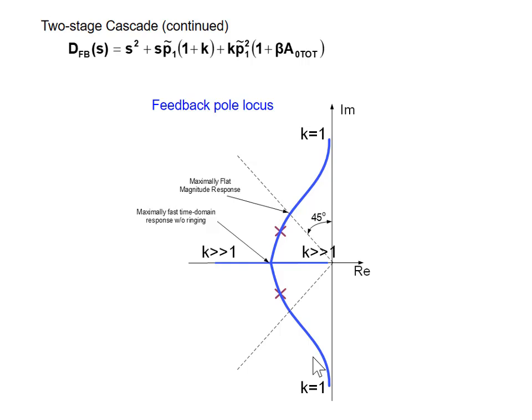Yeah. The comment was we usually try to separate the poles so that they lie between here and here, just slightly, maybe barely on the negative real axis or slightly off the real axis, but not any more than 45 degrees up. Why don't we go ahead and, it's easy to make K bigger and push them down here so they're widely separated on the negative real axis as well. Very easy to do that. Any idea why we don't?